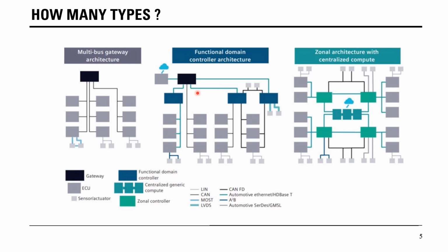Also we can see there is an Ethernet communication and other LVDS communications happening between different kinds of peripheral sensors or actuators like cameras, and we may use the LVDS interface. And CAN-FD is used between different local ECUs which are delivering specific functions in the vehicle.